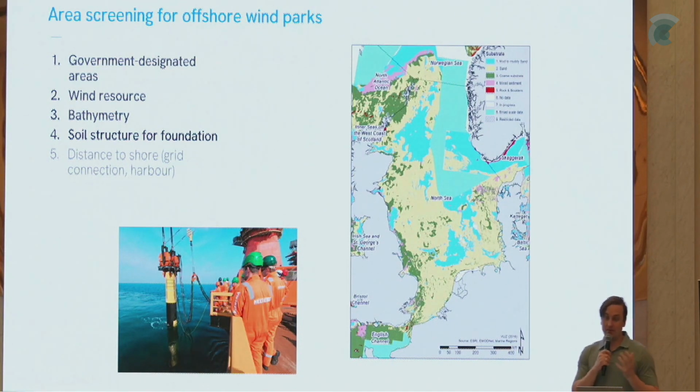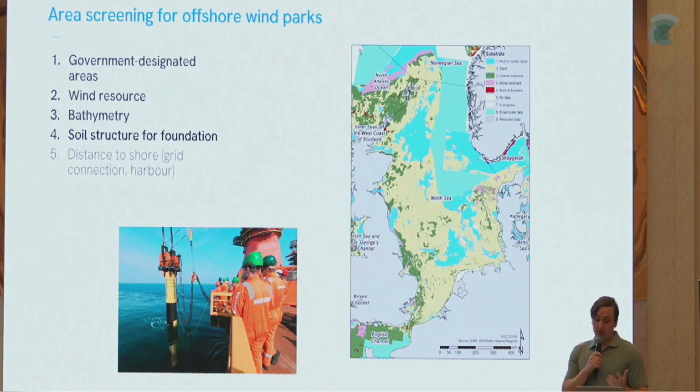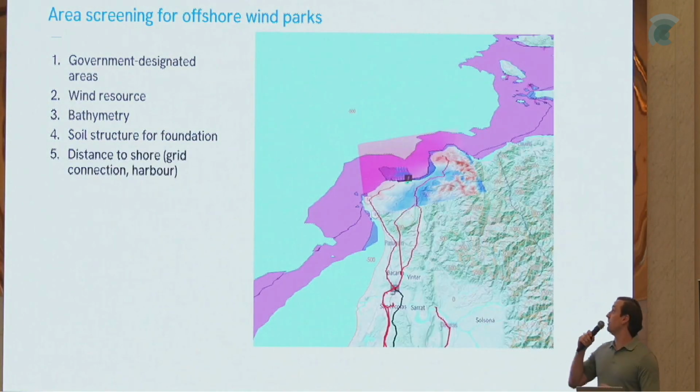So it's not only enough to have bathymetry, you need to know what's below also. So is it a rocky seabed? Is it muddy? Is it very sandy? This has a massive impact on the cost of your foundations and will decide if a project is viable or not.